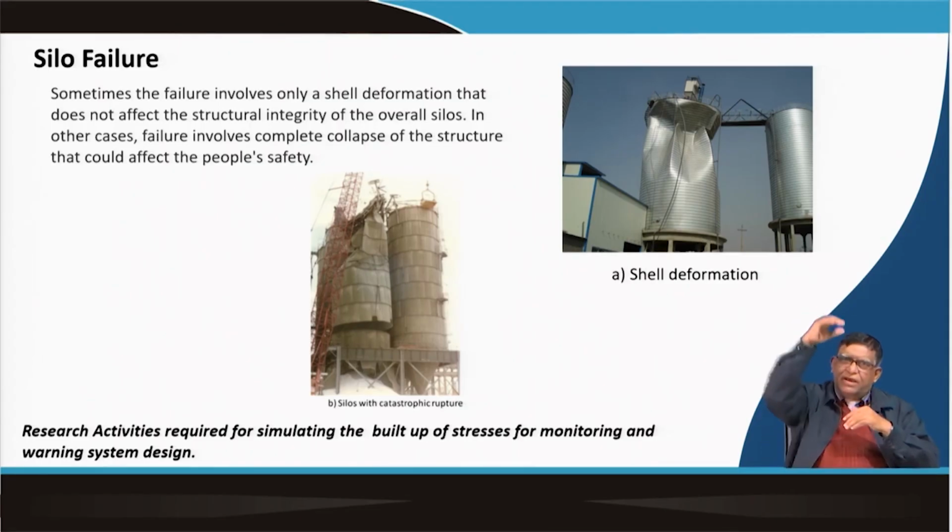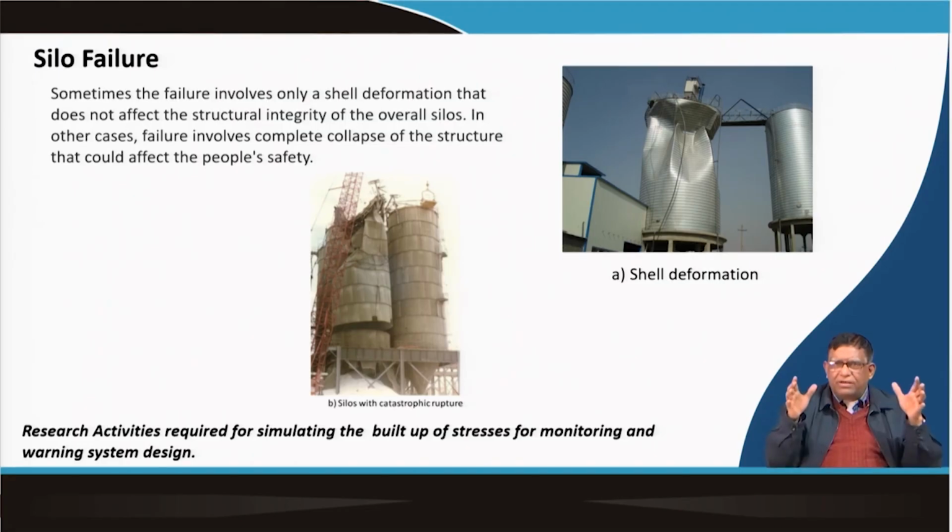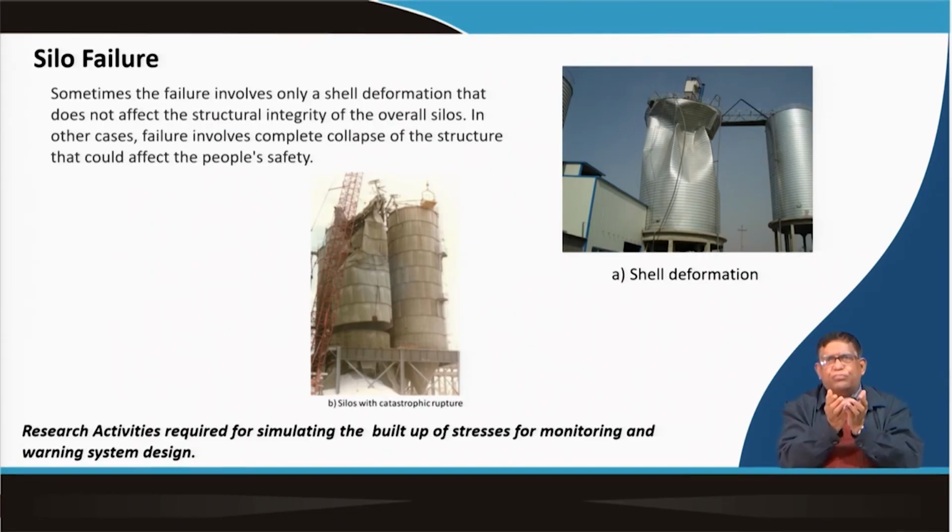Suppose we have 20,000 ton of material here. When the shell expands during the daytime, the grains will settle. But at night when it contracts, will it be able to push the whole column up?